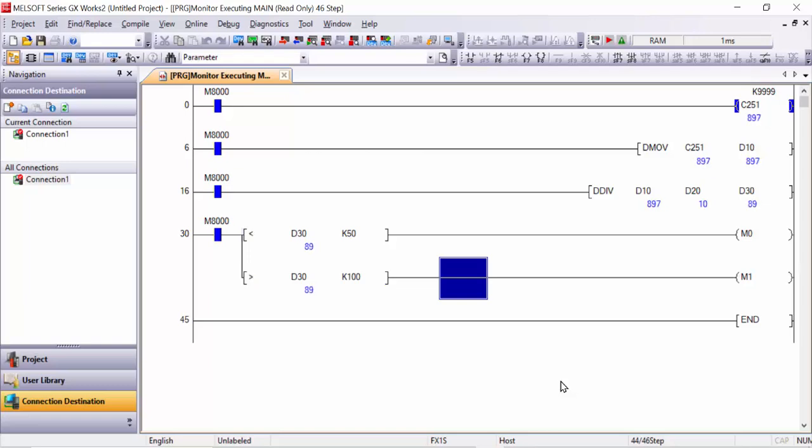So I think this is the easiest method of measuring the length. Any mold machine or any CNC machine or whatever, you can measure the length by the encoder. You can install the encoder at the back of the motor, and when your motor travels on, off, reverse, forward, you can decide where you would like it to stop, where you would like to start, and how much length you can see at this data register. And this data register you can simply take to the HMI, and you can physically see the original value of your length.